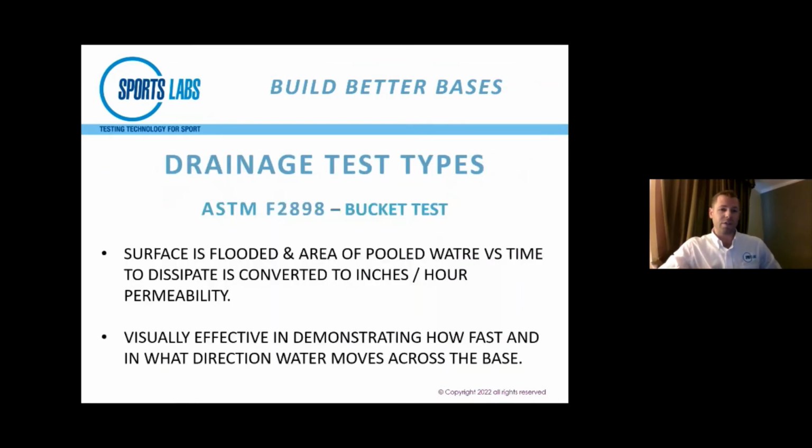We also have the bucket test, or the non-confined test. This has the advantage of being a little more visually descriptive. So this is where we're flooding the field with 50 gallons and then 25 gallons, and you're able to see how fast this water moves across the surface, what direction it's moving. Ideally, it goes straight down and goes away. That doesn't always happen, and so just visually, it covers a lot more.